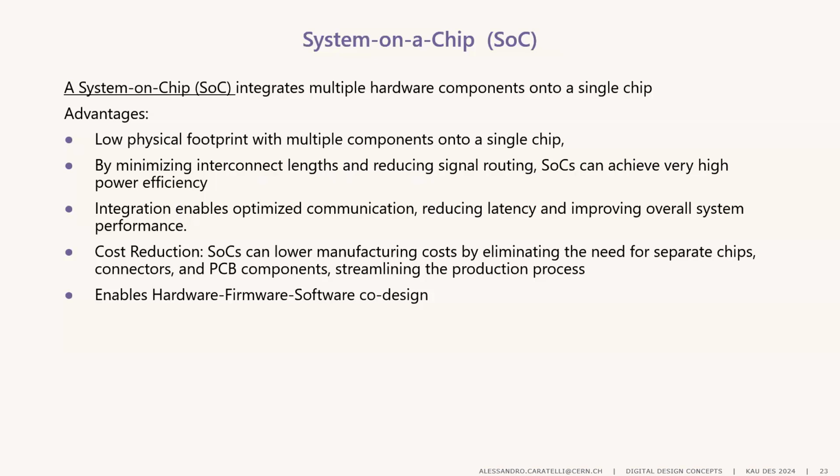And then another category is what we call system on a chip. System on a chip means that you're integrating different things in the same chip. You integrate multiple hardware components into a single chip. It can be a CPU with FPGAs, like for instance Xilinx or Altera, Intel and AMD actually now, provide these objects which are FPGAs with CPUs and other dedicated hardware resources embedded inside. Or it can be a system based on a CPU with different hardware accelerators around, or mixing multiple functionalities, like in the case of the chip I'm working on, which is a pixel array custom for an application, but it also has some configurable and programmable objects inside. So system on a chip means to put together multiple types of hardware into a single chip.